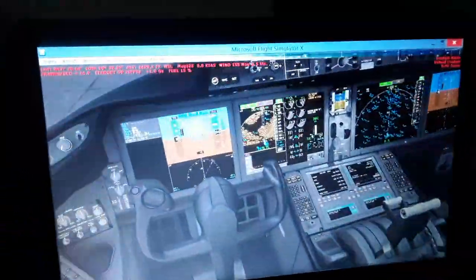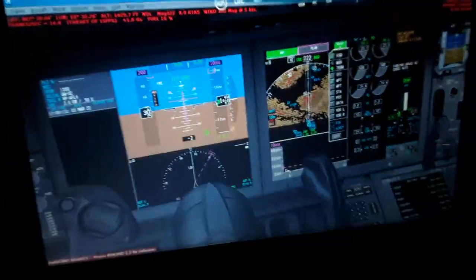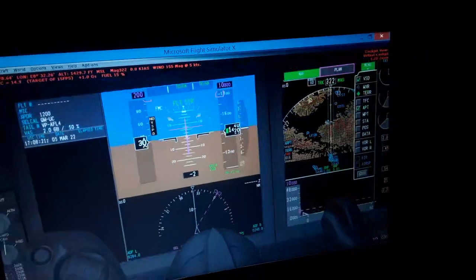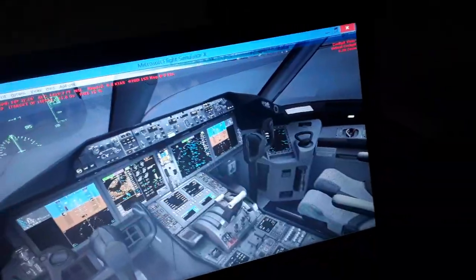During the whole flight we're going to burn fuel, so the center of gravity is going to be shifted and recalculated. Also, this will give us the mean aerodynamic chord position of the forward wings, the stall position using the mean aerodynamic chord, where the maximum aerodynamic lift occurs in the forward wings. We have also the stall, so we need to monitor the stall. Over here in the airspeed tape, we have also the stall displayed when we fly, with a red and yellow indication, yellow and red below the airspeed. We need to keep an airspeed above the stall when flying. So we're gonna use flaps 15 degrees and also the horizontal trim stabilizer 4.25 degrees pitch up.